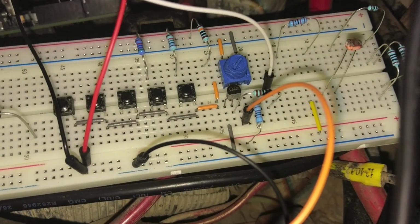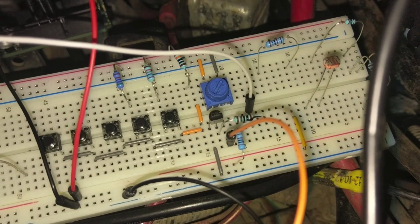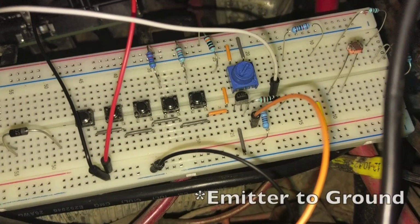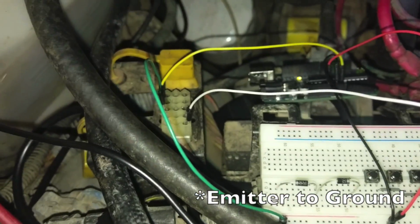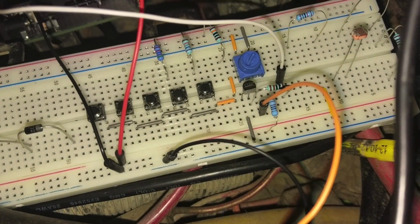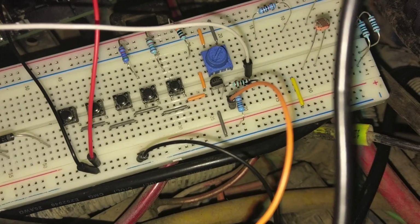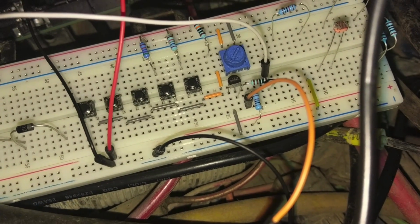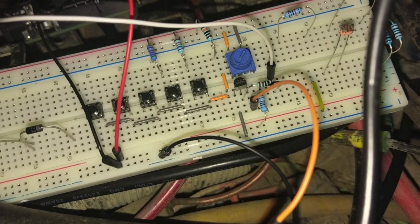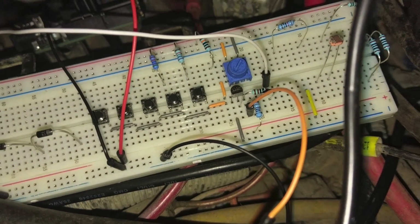So all I really did was I took a transistor and I ran the base through a resistor into the TX pin, and then obviously the emitter goes to ground, and the ground is just connected to the car over here. And by hooking the logic analyzer up to the collector, which is using a pull-up resistor over here, when the TCU pin goes high, it brings it to ground, and when it's not high, the pull-up resistor pulls it up to 5 volts.